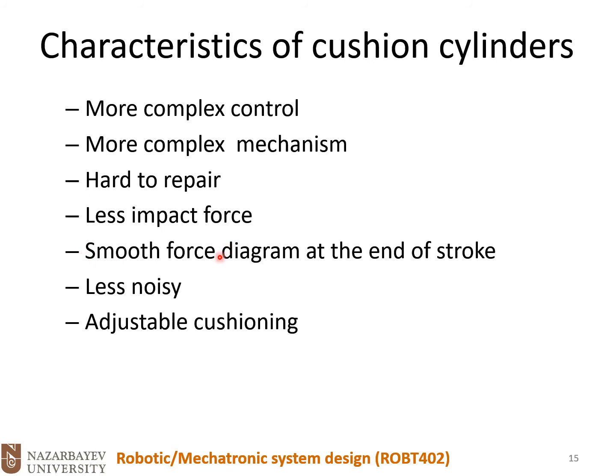So force is constant, but when it comes to the ends of the stroke, then the force changes based on the cushioning level and opening of the set screw. We have less noise because we don't have that banging at the beginning and end of the stroke, and we have adjustable cushioning in many cases.